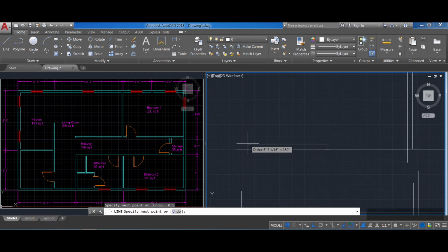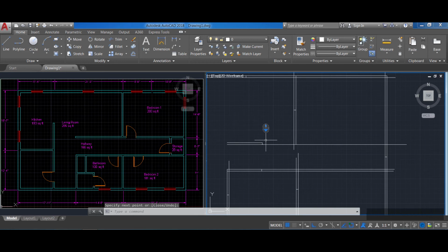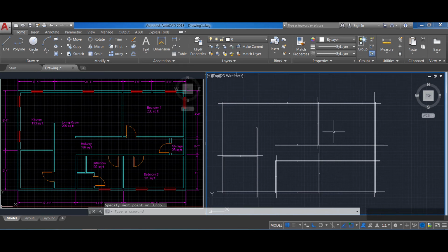I wanna get this line exactly at this length or this end of line. So what I do is I move to the left and I hover on the endpoint, and you see that I have this green line that is helping me and snapping into that endpoint. It's really, really useful. So I'm gonna keep going here, and I'm gonna draw this all in that. And that's it. I think we have all our inner walls of the rooms, and the next step is gonna be, I'm gonna clean this up by taking all these extra lines out.